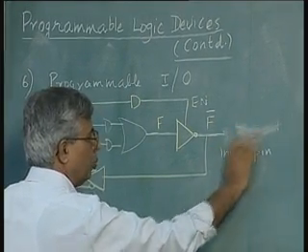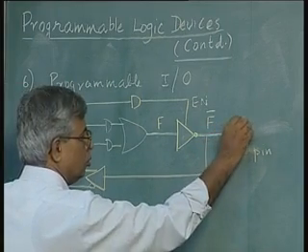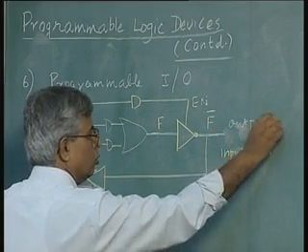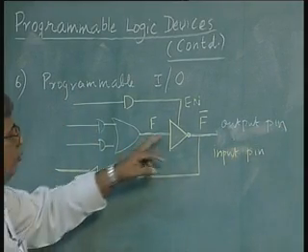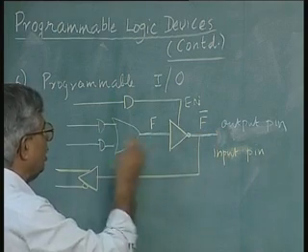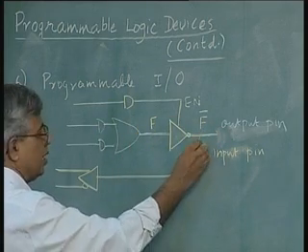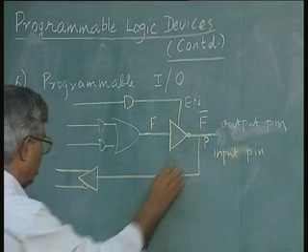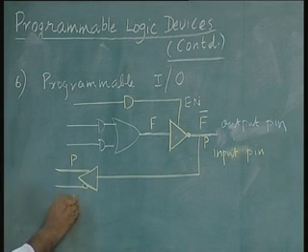Earlier it was an output pin, and if you disable this gate, this becomes an input pin, and I can give a totally different function. To the f, I can maybe give another function, let us say p. So, this p becomes an input to the device or your AND gate array, p and p bar.